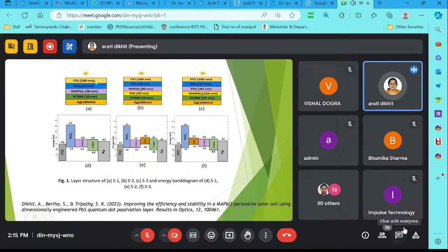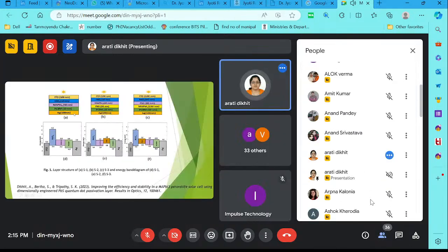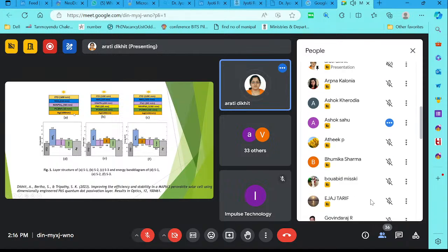We have one glass layer, which is the ITO layer, transparent conductive glass, and then we have taken NiOx, nickel oxide, as the HTL material, the hole collecting material, and this is our active region. PCBM is the material taken as the ETL, or electron transport layer. And this silver we have taken as the back contact electrode.